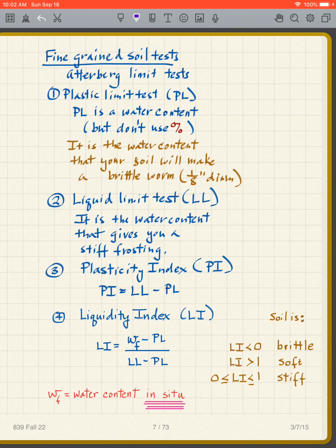Generally, flour is flour. I add a certain amount of water to flour, it creates a paste. You get it in the recipe. But soils are different. In other words, the soil in Boston is different from the soil in San Francisco. So you add different amounts of water. So the plastic limit for the Boston blue clay, in other words how much water needed to be added, is completely different for San Francisco Bay mud.